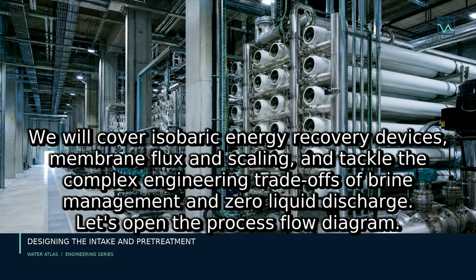In this episode, we examine how modern plants optimize specific energy consumption, deploy isobaric energy recovery devices, manage membrane flux and scaling, and tackle the complex engineering trade-offs of brine management and zero liquid discharge. Let us open the process flow diagram.